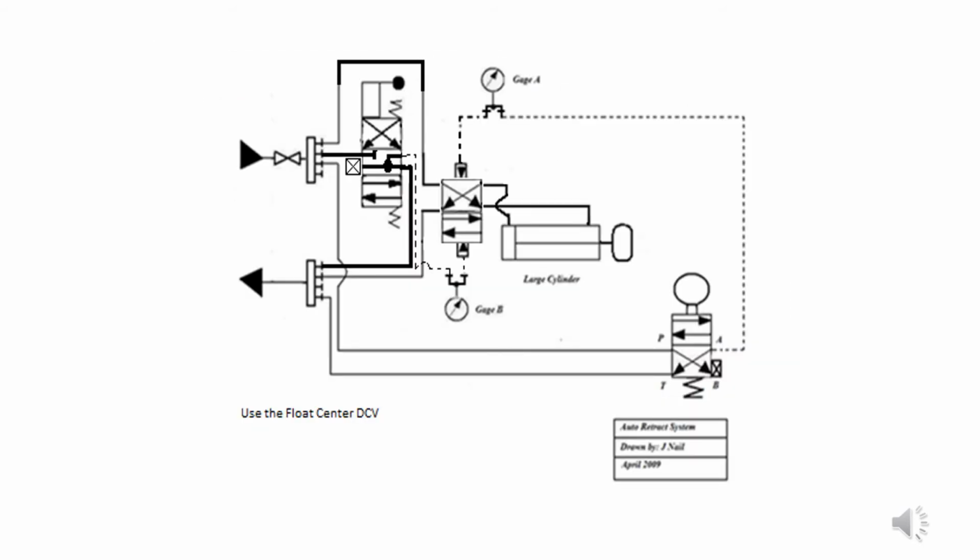This is a hydraulic automatic circuit, and it appears on page 142 of your lab manual. The operational principle of the circuit is that with a single input, an actuator will perform a complete function, extending and retracting without any intervention of the operator. The cylinder extends, reaches a limit, and then returns, and then the cycle is complete.